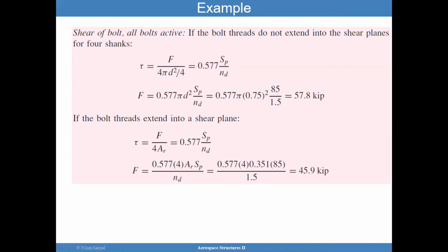We can also look at whether the threads do extend into the shear plane, and if they do, the area will be smaller than what was considered in the previous calculation. So in this case, the thread did not extend into the shear plane, but in this case it does. And if it does, the force calculation will be reduced because the threads cause the bolt to fail a little bit earlier due to the stress concentrations at the root of the bolt.